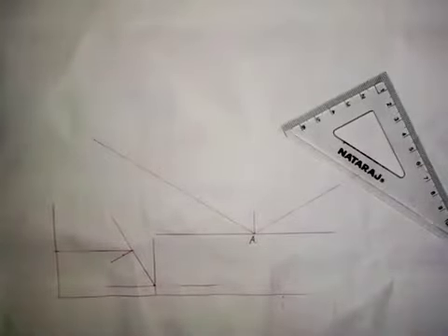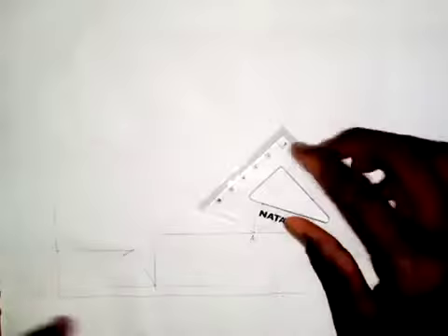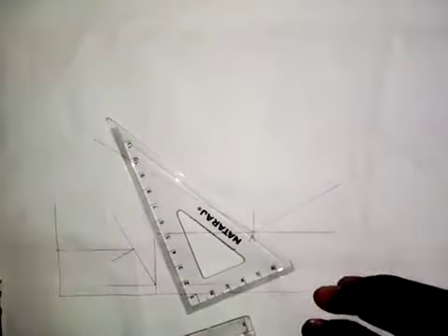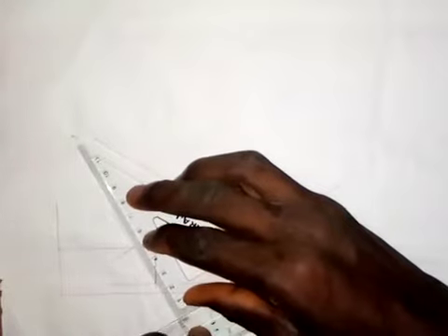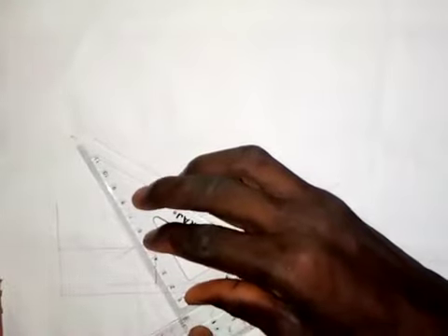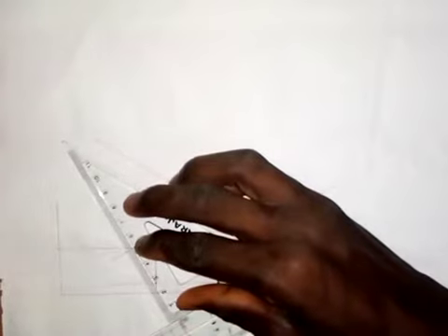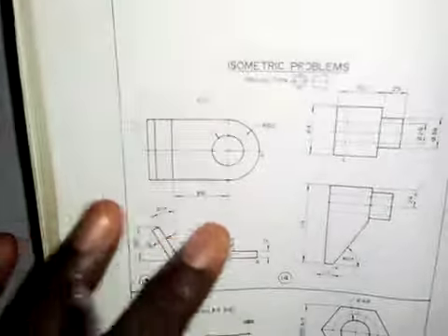So with what I've done now, the next thing I'm going to do is take my ruler. I will set this set square on this line and support it with my ruler like this. Then I will shift the set square to this point where we have taken that measurement of 6 millimeters. Looking at what we have here, I only need this part. I don't need to draw everything as we have in the diagram. This is the part that I want to make use of, so that's why I didn't complete it.